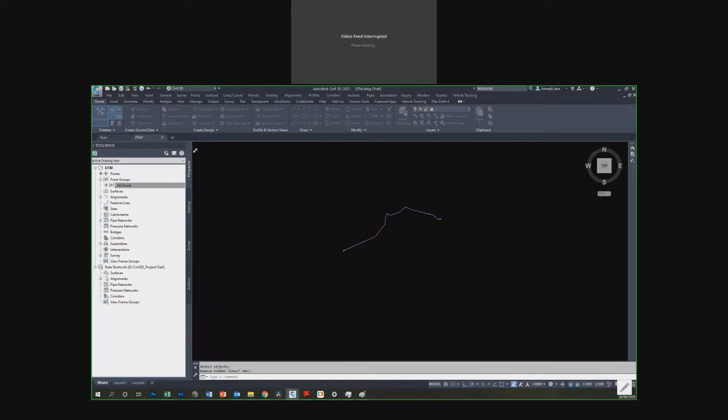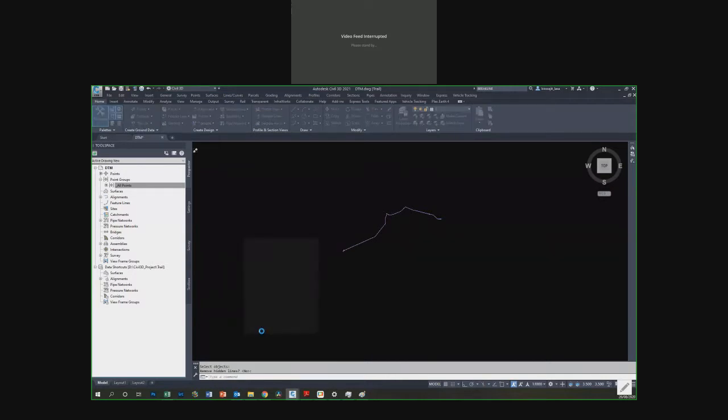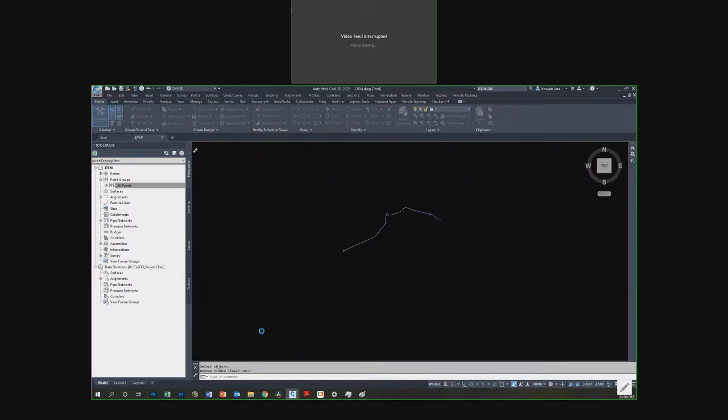This is something which you should do. In the DTM drawing, in the base plan drawing, first convert it to 2D line and then bring it to Civil 3D. That will be an easier part, because this one has points also. So now it's replacing all the points, whatever it has, the z values in it.